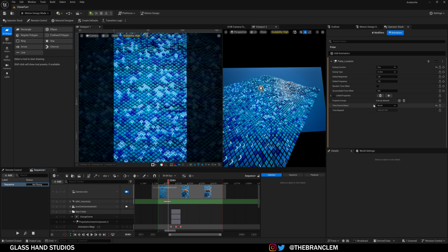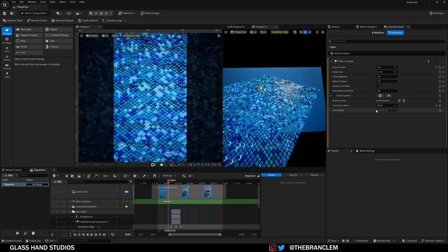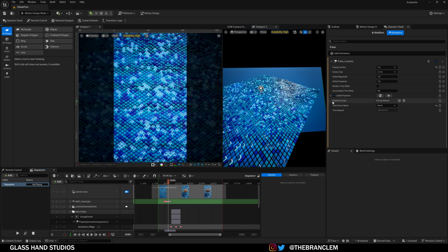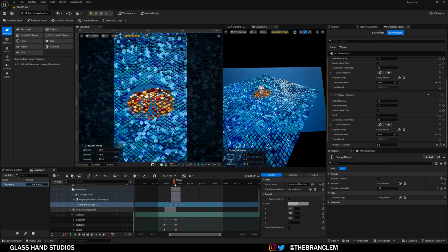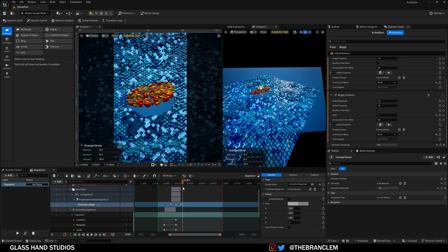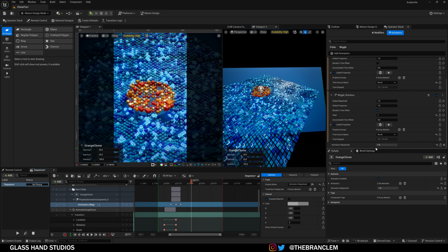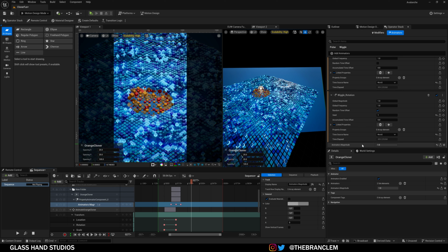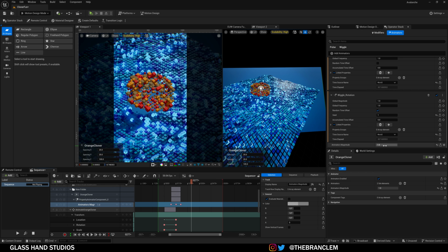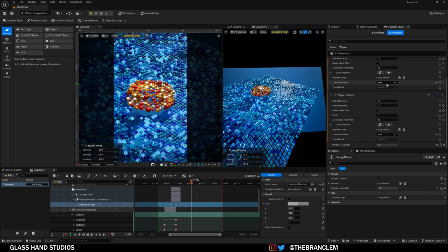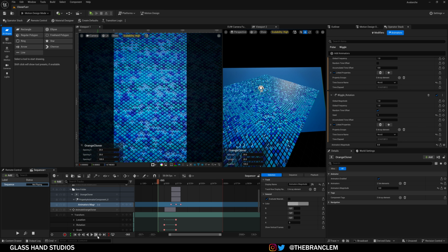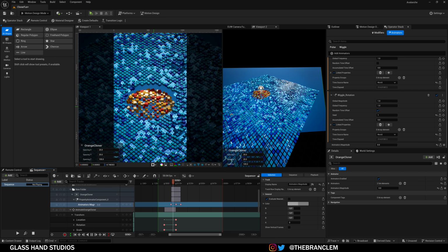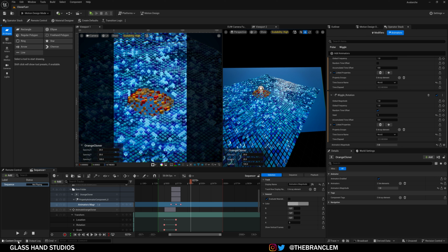And these are turned on based on the world time. So if you scroll all the way down to the bottom, there is an animator's magnitude down there, and this will turn everything on above it. So anything that's in this list, this little animator's magnitude slider is super handy to animate, so that the world time, as you see, completely keeps going on and on. And yeah, that allows that to pop on and animate. So that's pretty much this example. Let's move on to the other one.